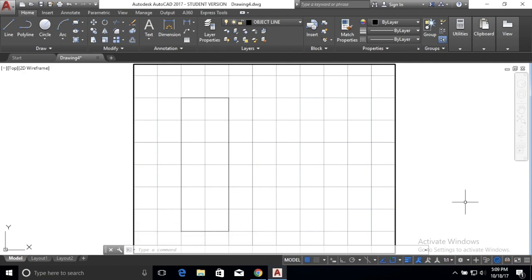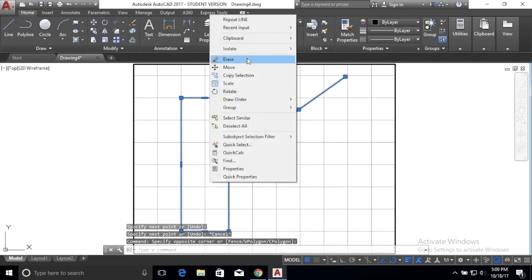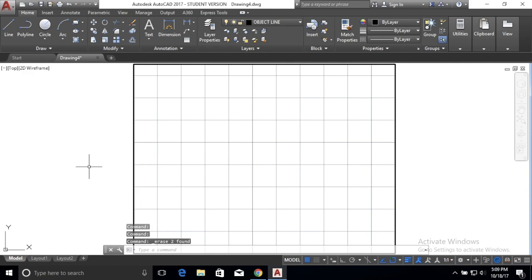You can also use the line tool and do something similar. If I want to start the line tool at 5 comma 5, and then I can draw and click wherever I want it to end, or I could type in a number as well. Now, let's say that instead of absolute coordinates, which is what we just did, we want our coordinates to be based off of the last point that we clicked. You can use the @ symbol on your keyboard and type that in to let the computer know that whatever you tell it is based off of the last point.